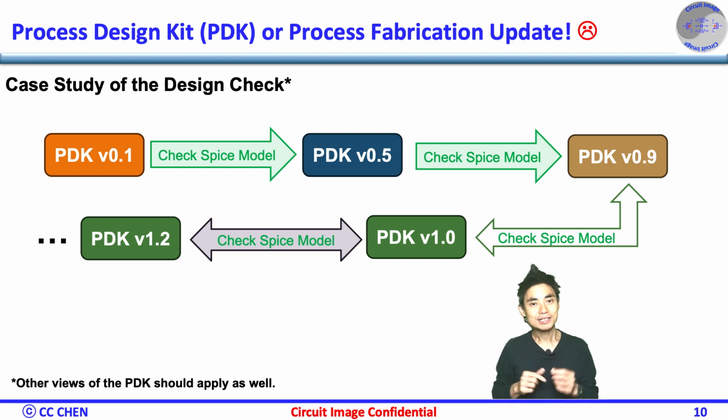Correct. The process design kit, PDK, will keep updating from the foundry, since their process verification will also update because of several reasons we are not sure. Therefore, it's likely the PDK has been changed during your porting phase, which could impact area, floor plan, tempco, precision, etc. Another possibility is that the PDK could change after you tape out, over different wafers in time.